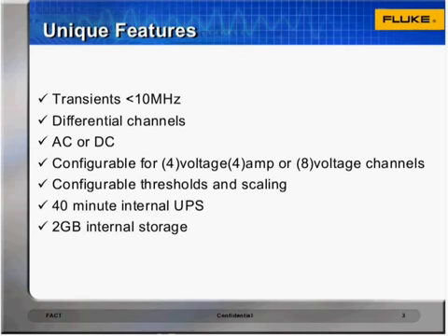But don't let all those choices scare you. The instrument comes fully loaded with defaults to allow general monitoring right out of the box. The 1760 also has an internal UPS lasting up to 40 minutes to allow the capture of power being restored from most outages. All the data is stored on an internal 2 gigabyte solid-state drive. It also has the ability to transfer data via an external compact flash card slot or a USB thumb drive, in addition to common Ethernet capability.